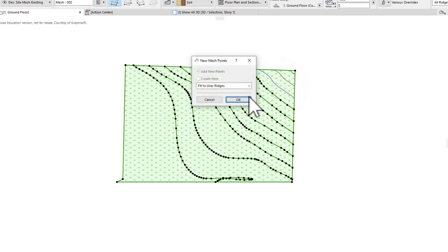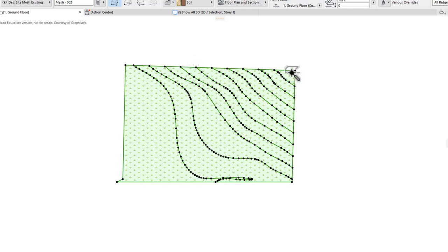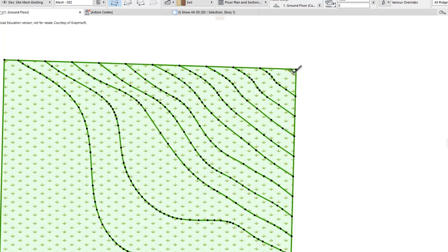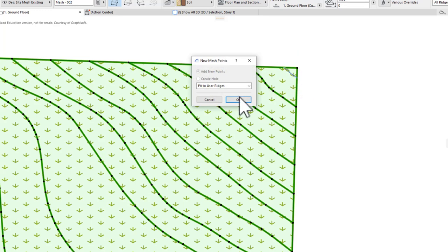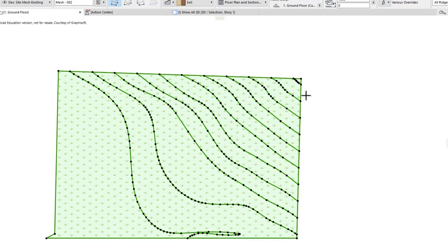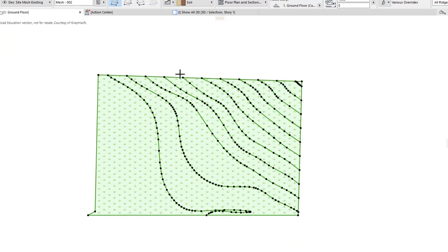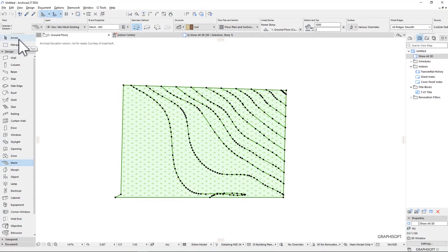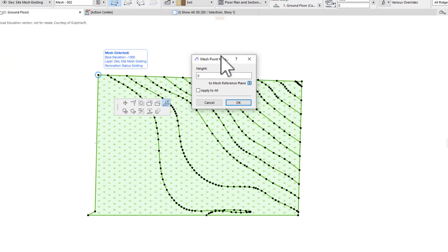Now it's handy to have your Mojo next to you so that you can check the coordinates or the elevations, because I need to, let's zoom in here, make sure I've got that one. Okay. So on my Mojo tool, I can go around to the corners and check the elevation of each corner. So I click there. Now if I look at my Mojo tool on my phone, I can see that that spot level is 48 millimeters. So 48 millimeters, but if this is above, this is project 0. So I'm going to use that.